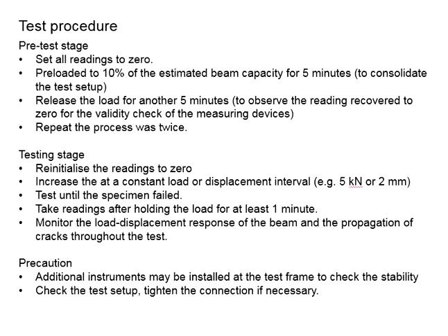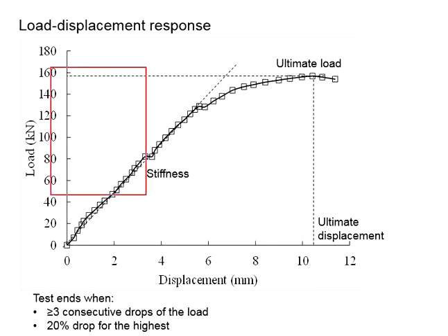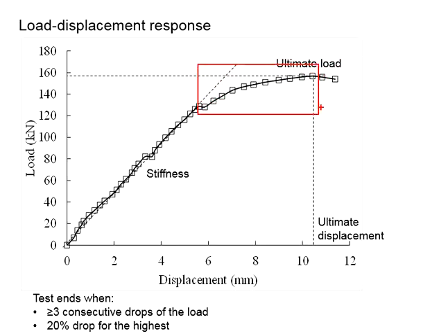If you find the plots are too closely congested, you can enlarge the load interval. Or if you observe the plots are too far apart, you can narrow down the increment interval. The load displacement response also helps you to identify the stages of the specimen. For example, at the early stage, the specimen remains more or less elastic. The development of the displacement is slower. And then at the later stage of the testing, the displacement of the specimen increases faster.